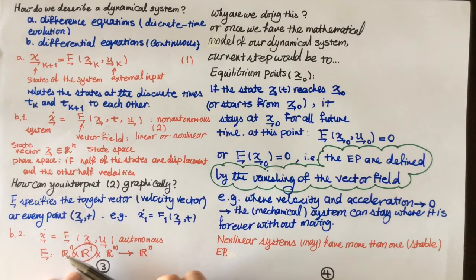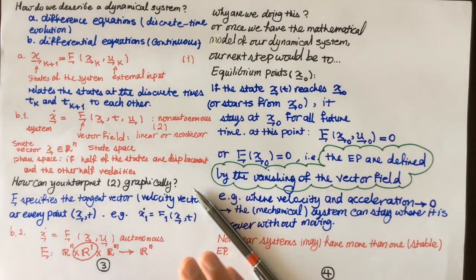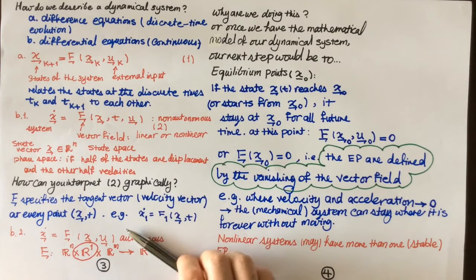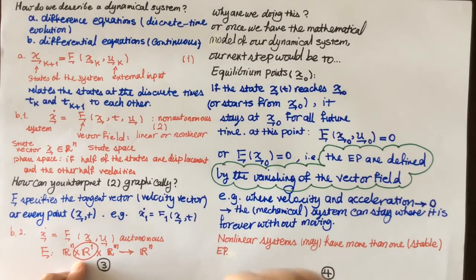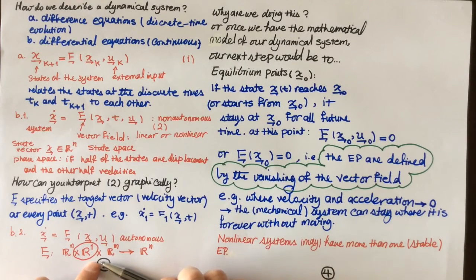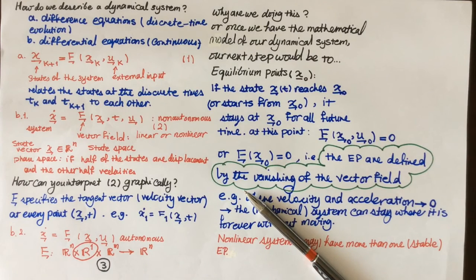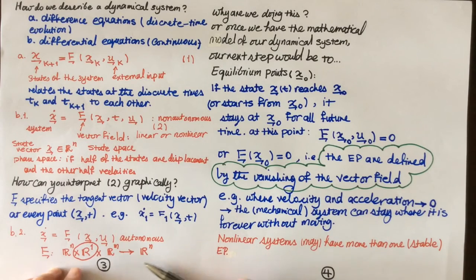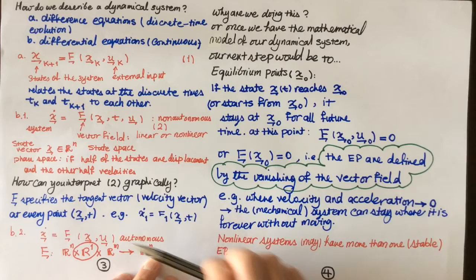The other thing is that when we say mathematically that x dot is a function of x and u, essentially f is a mathematical function which maps R^n, assuming our state vector has n dimensions, cross R^1 if it was a non-autonomous system, because time is a scalar quantity, cross R^m because our input could have m dimensions. m is not necessarily equal to n, the number of state variables, and this function maps this vector field to this n-dimensional vector field x dot.